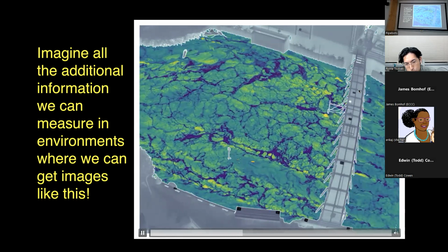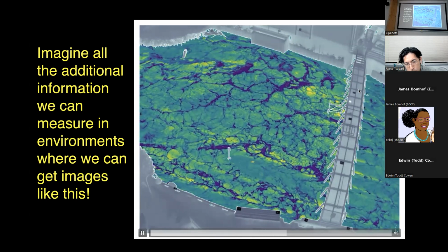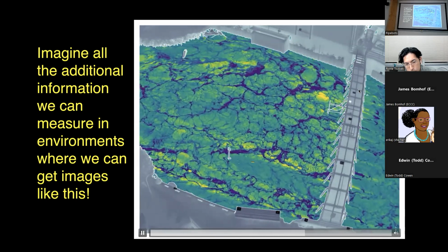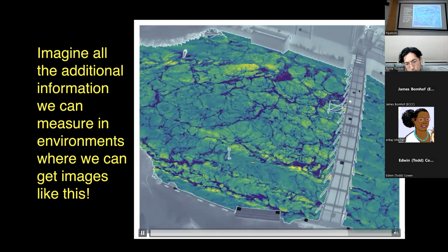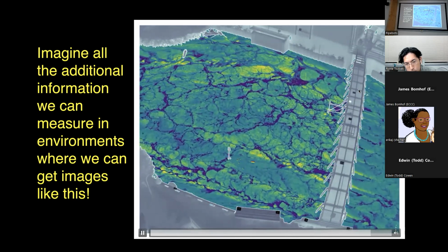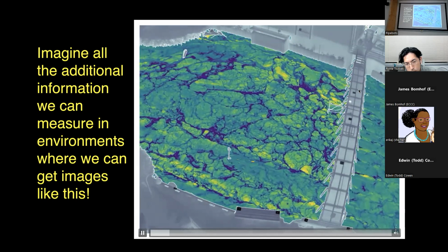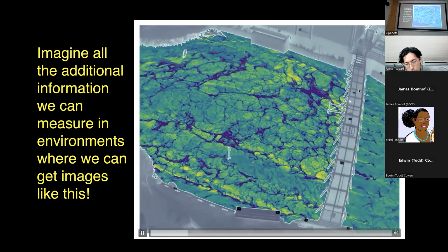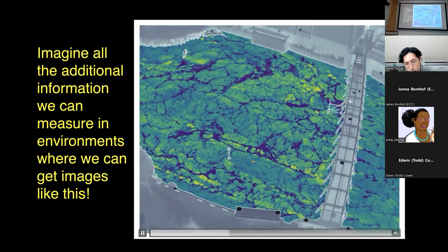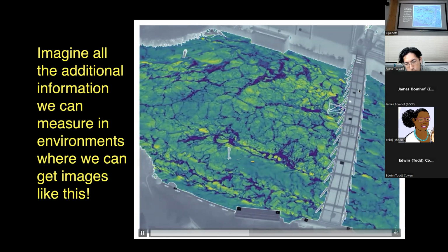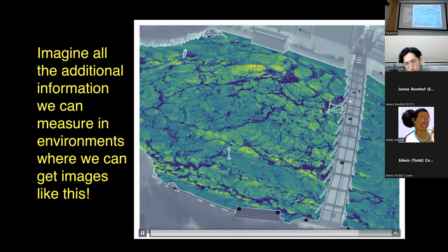The main issues that can impact it would be some other shear layer. Two come to mind: if your flow is stratified, so deeper rivers and low turbulence conditions, or, as we saw in the previous talk, macrophytes can lead to a very strong shear over the canopy, and you'll get a false sense of what those scales are. But if you have a relatively well-stirred flow without macrophytes, it works quite well.